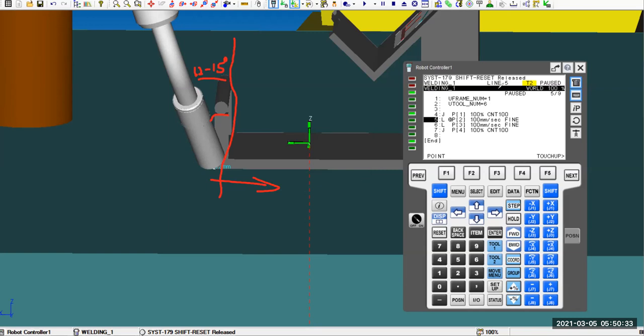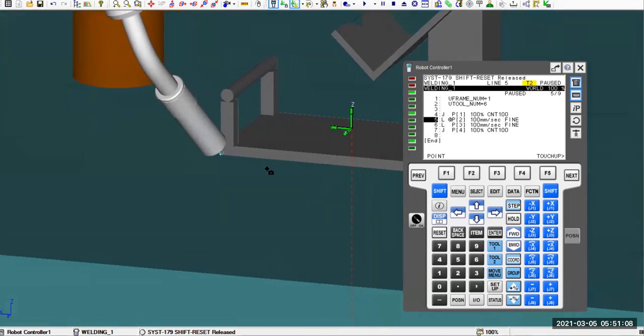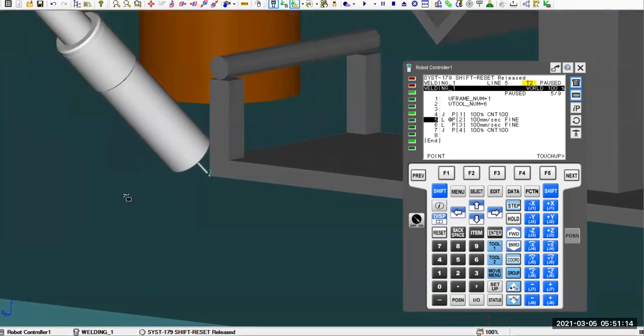All right. Again, and also speed, right? Over here, I just chose a random speed, and you understand that definitely is going to make a huge difference on the result of welding, right? So I'm just talking about the basic setup on the welding. If you go into the industry to work with this type of application, for sure they will have detailed requirements. They even have a welding tag to check the result of the robot welding. All right, over here again, I just want you to know that this sort of requirement exists, so it doesn't just happen randomly.